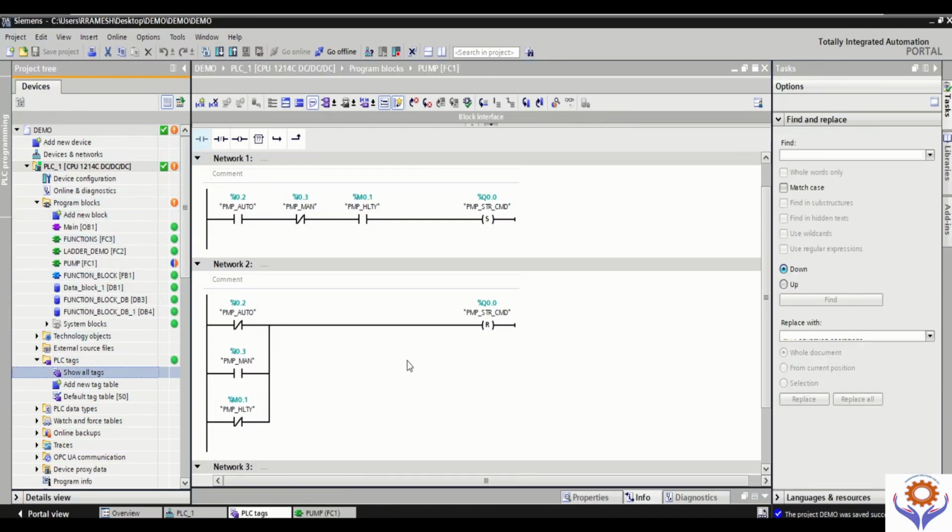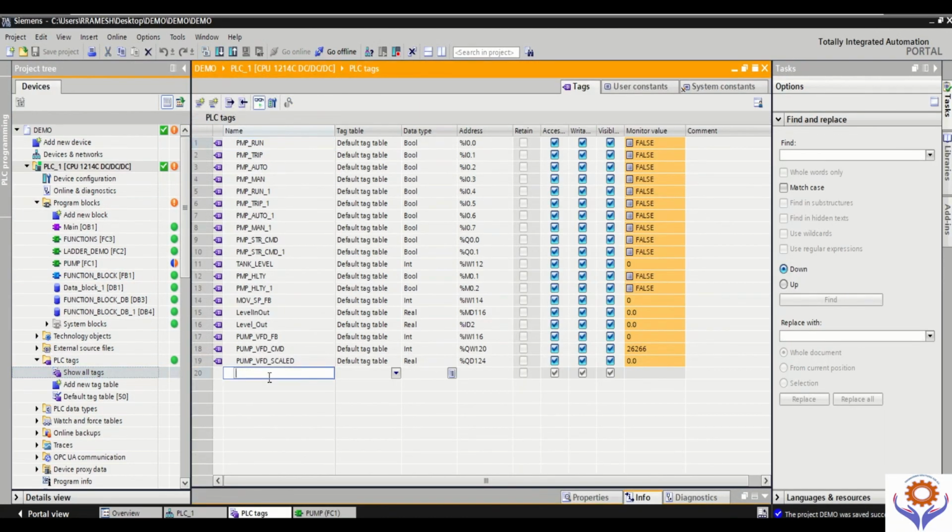And if you go to the PLC tags, I will add a tag called modification. Once you enter it, you can see this has become completely orange, because this one is modified already. If you click there, it is showing a difference in lower level comparison. This means there is something modified. So if you go online, you can find this type of modification.